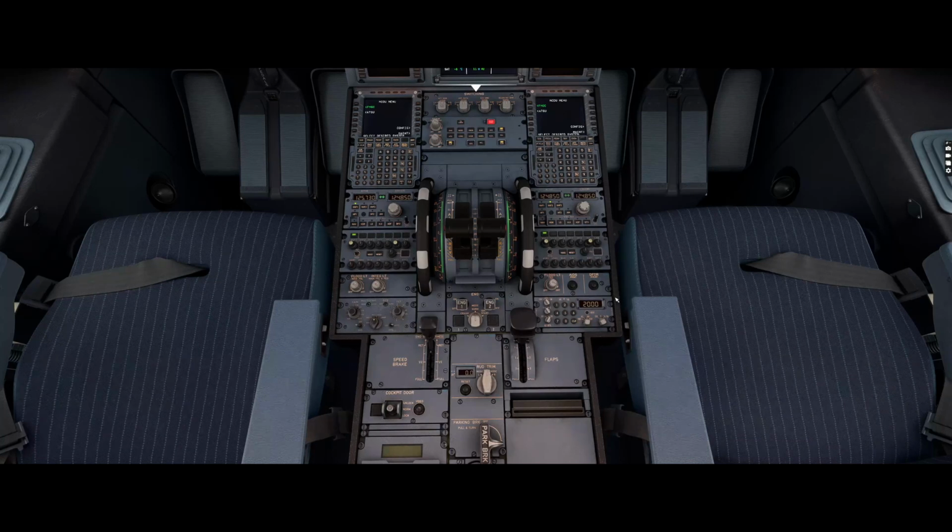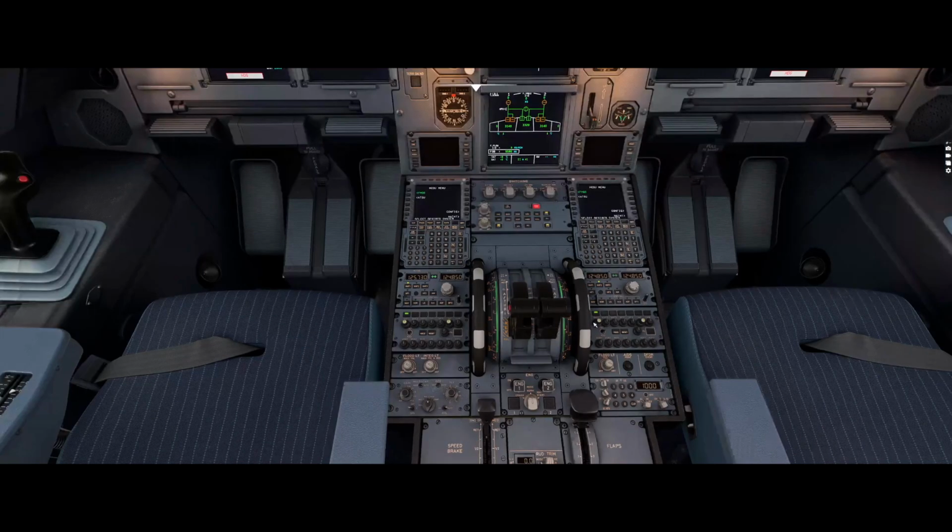So usually clearance will give you your squawk code, which you input into this little box here. For the sake of this, I'll make it 1000, for example. So you type in 1000, set your transponder to auto, and that'll be that. Here's your little TCAS setting as well. So TCAS is always kept on standby, but turned on to TA only before takeoff.